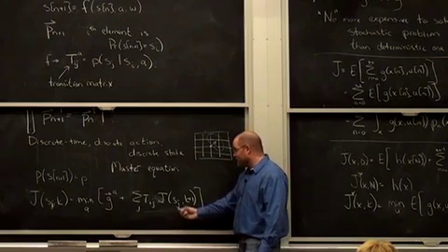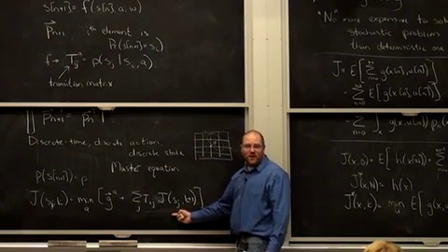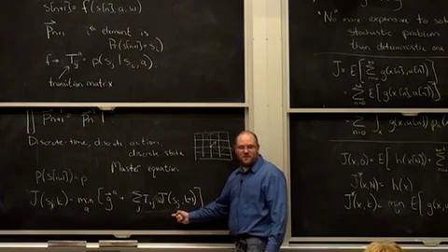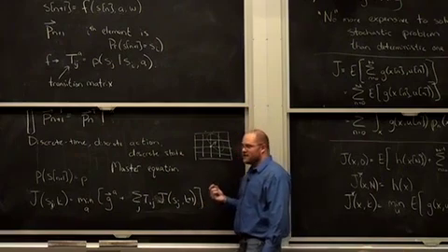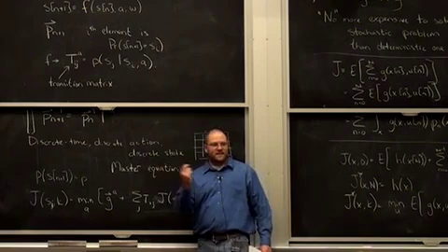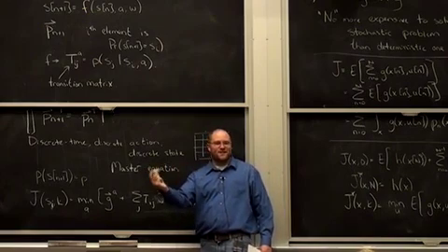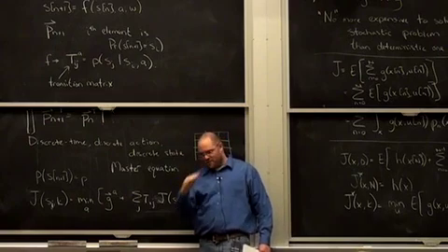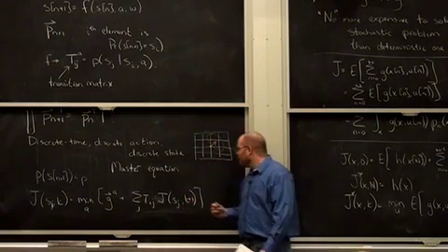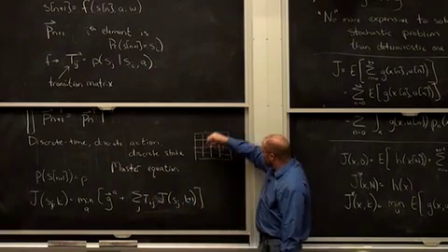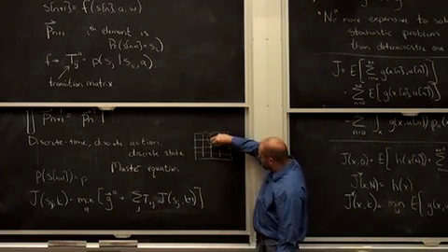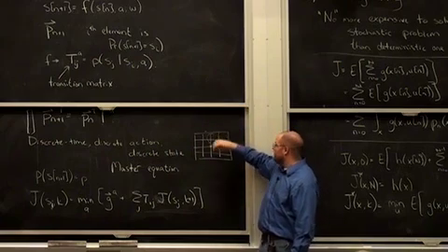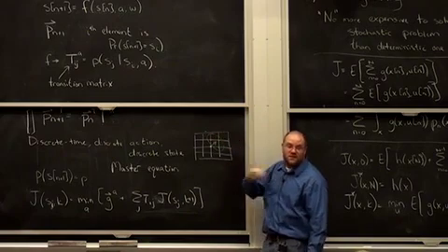Simultaneously, or maybe conversely, this actually tells you why we have problems with the barycentric interpolators. Remember, the fundamental problem with the barycentric interpolators was that things sort of leaked away from the nominal trajectories, and we had our chattering happening, and our bang-bang solution wasn't quite right. Now you can think of it as my deterministic problem assigning some probability of going to each of these neighbors, and you can see that distribution is going to start slipping away from the nominal trajectory.